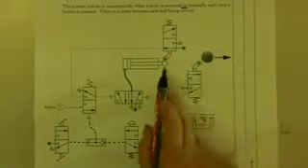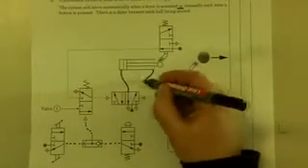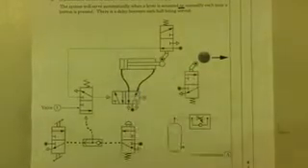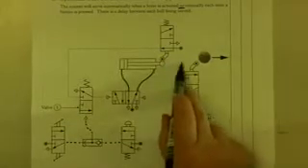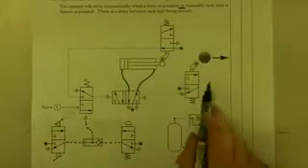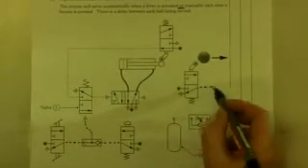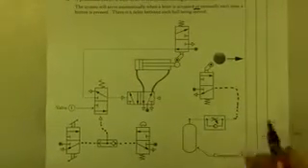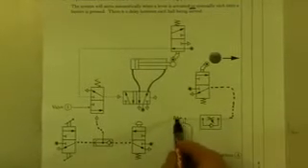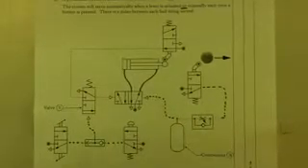Now at some point the double acting cylinder will instroke, and so it must be connected on both sides to the 5-2. However, let's have a look at how it instrokes. When the double acting cylinder outstrokes, it hits this roller trip. The roller trip then can send air, pilot, through a restrictor into a reservoir. When the reservoir fills to the correct pressure, pilot air is then sent to the double acting cylinder, and that completes the piping of the circuit.